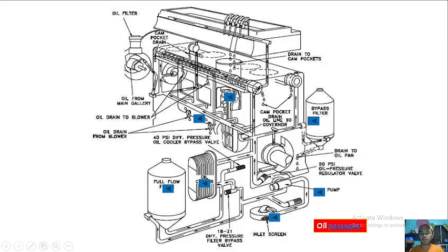It will regulate the pressure entering the system, to the crankshaft, into the governor, to the blowers, to the oil main gallery, to the turbocharger, to the cam, to the crankshaft, to the piston cooling also, and to the bypass filter going back to the sump.